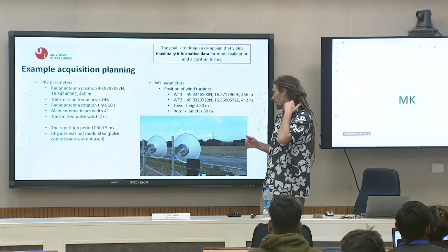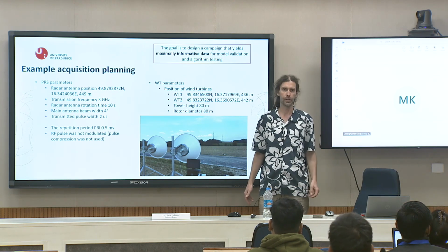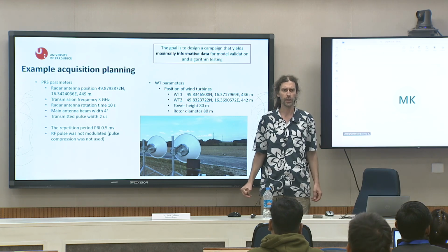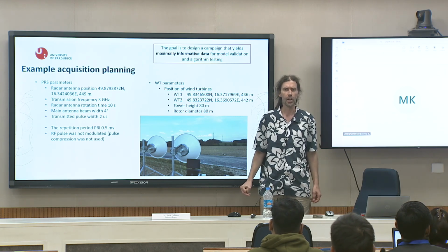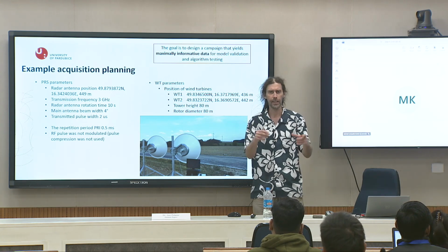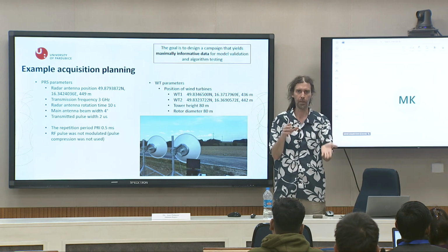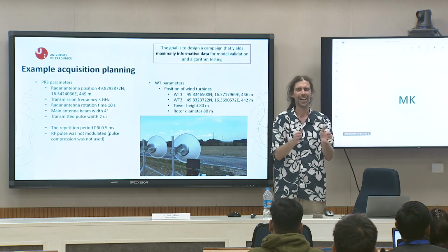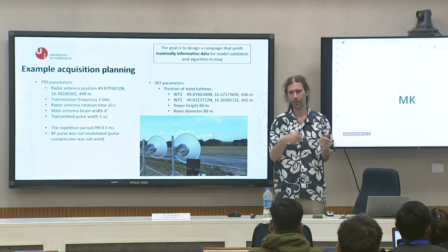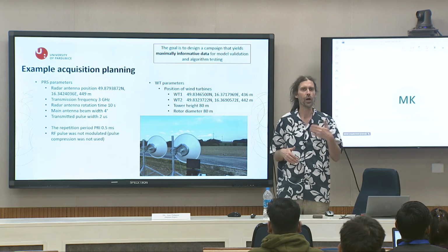So we make recording from 6 up to 18 seconds due to data rate limitation. Not on our hard drive, there was enough space, but the problem is with the SDR. If you have bandwidth 40 megahertz, there is some cache memory, and after some time this cache memory starts overflowing, so we need to adjust.